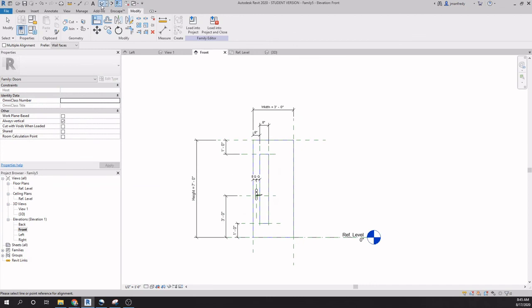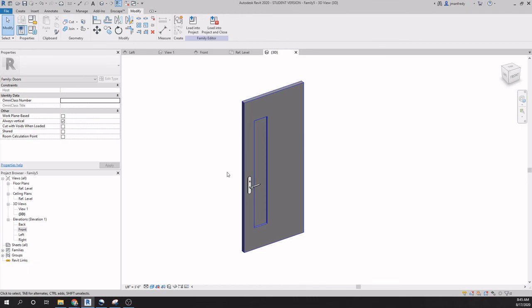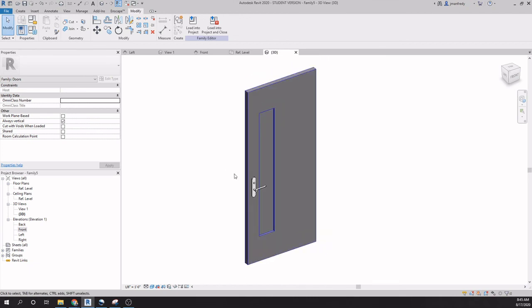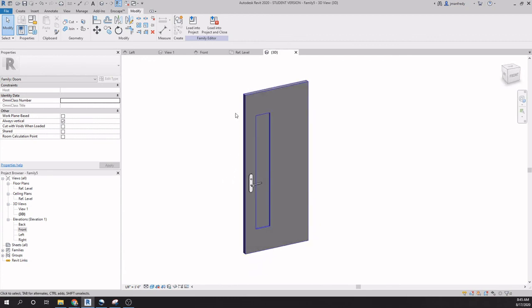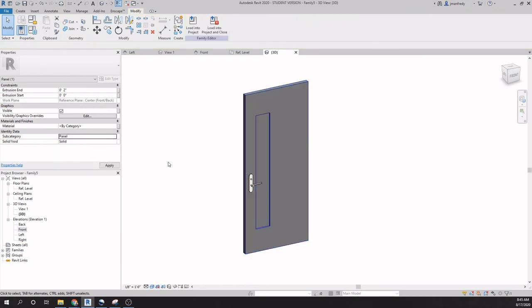Now, given that we've made this associated with the door category family, again, we did it here. It's a door, so when I hide the door category from my project, this door will disappear, as opposed to it being the generic category. I can also assign these to subcategories. So I can tell this door here, for example, to be associated with one of these options here. And this is describing a panel. So I will choose panel.